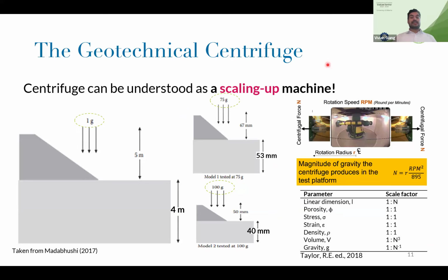So, the geotechnical centrifuge. I'm pretty sure that most of you already know this, all the theoretical background that is behind this. So what you do is you have your model, and you have your prototype, the one that you want to model. So you create little models, and with the enhanced gravity, so when you are in a hypergravity environment, the stresses here distribute like they are here. So you can have little models that represent huge things, and the models are related with the prototype through what we call scale rules, which are just a list of scale rules.